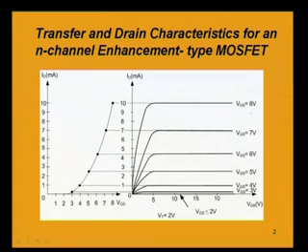Similarly, for different values of the gate to source voltage, we have these plots, and by the side of it, if we want to draw the transfer characteristic, then we must plot, for a particular gate to source voltage, what the saturation drain current will be. That will give a point. Joining all these corresponding points, we will get a nonlinear curve, that will be the transfer characteristic. That is the characteristic between the drain current and the gate to source voltage.